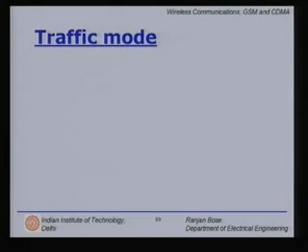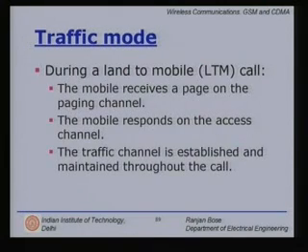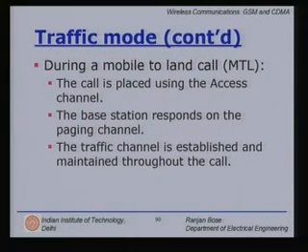So, we come back to traffic mode. During a landline to mobile call, the mobile receives a page on the paging channel. The mobile responds on the access channel. The traffic channel is established and is maintained throughout the call. So, the same PN sequence is maintained. During a mobile to landline call, the call is placed using the access channel. The base station responds on the paging channel, and the traffic channel is established and maintained throughout the call.